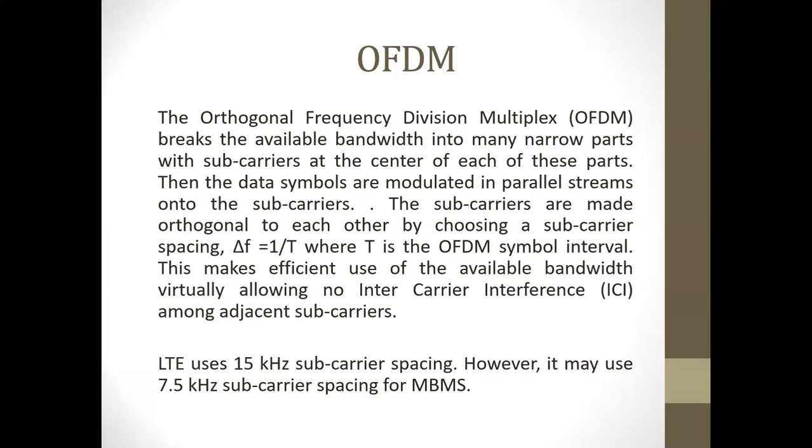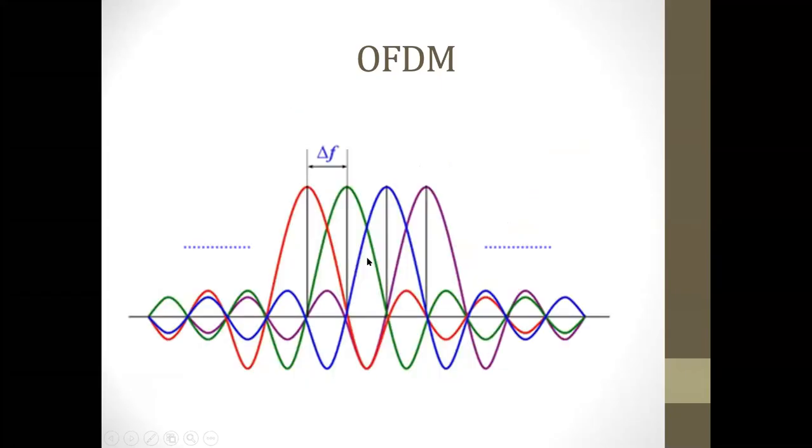People didn't go for this type of use of multiple subcarriers, because when you do that, you need to use some margin. Otherwise, there will be interference between your carriers. So normally, if you don't use OFDM, meaning that if you don't maintain this relationship, then you don't have this kind of orthogonality.